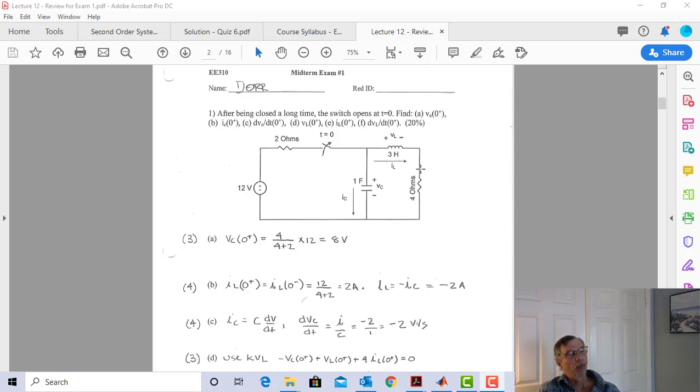Ask an old person who worked on vacuum tube radios, and you'll unplug the radio and you might go in with your hands and get a 300-volt shock. Old people call that a doghouse circuit. So I'm careful about when I just say it's dead, but let's formalize that.